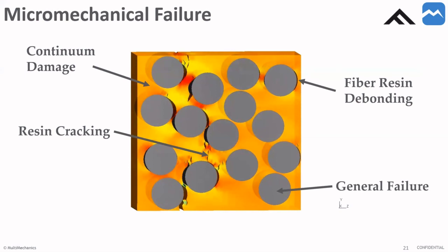This is an interesting question. I don't know if we have an answer to it, but how do you manage additive layer technologies in the RVE, in particular in terms of boundary conditions to apply between two superposed RVEs, one RVE per layer? So this is a common topic when we're looking at simulating additive manufacturing. You go layer by layer, so you're not only going to have your microstructure here, you're also going to have layers that are potentially weaker or resin rich, or what have you.